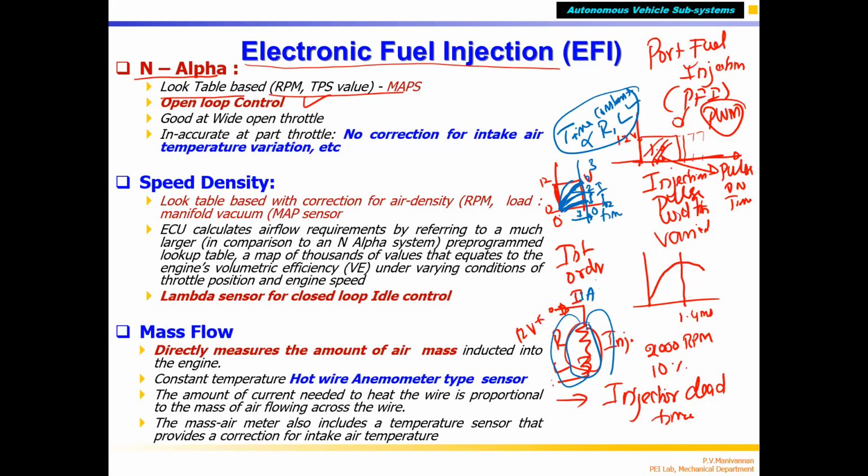Yes, sir. So you make a two-dimensional table, I told you, correct? Top is the percentage of throttle, 10%, 20%, 30 something, it goes up to 100% opening. Then RPM, engine RPM, starting with, for example, 2000 RPM, 3000 RPM, 4000 RPM, correct? 6000 RPM, make a table, correct?